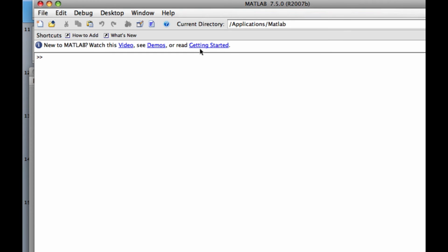And now is the time to apply the MATLAB function quad. So we write quad, example 2. We give the lower time interval, we give the lower concentration and the upper concentration. So we make the integration from concentration 3 to concentration 0.406, and we get 4. And that is the time it takes for the concentration to go from 3 to 0.406.